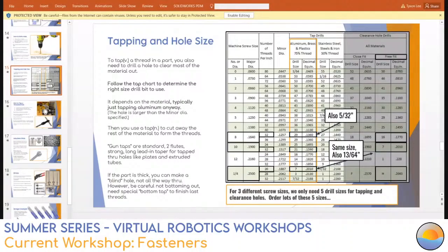Okay. Eli asks, if you need a bolt larger than a quarter 20, what size or sizes would you recommend? Someone else in chat did recommend a 3/8 as well. So you have that for your information. Sure, but there's also a 5/16, and then there's also 9/16. It really just depends on how big you're going. A half inch bolt, I couldn't imagine where we would need that on an FRC robot. The strength of a quarter 20 is so strong that you don't want to overdo it with these.